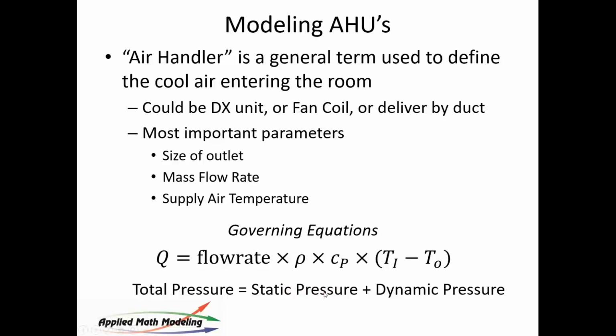In particular, when you're talking about containment, you want to try to maintain a pressure differential between what is in the room and what is in the contained area. And that pressure differential is important for maintaining a robust design. When you introduce velocity, that changes the pressure differential, and we'll see the effect of that in the CFD models. So again, total pressure is static pressure plus dynamic pressure, and we're going to watch these things trade off.